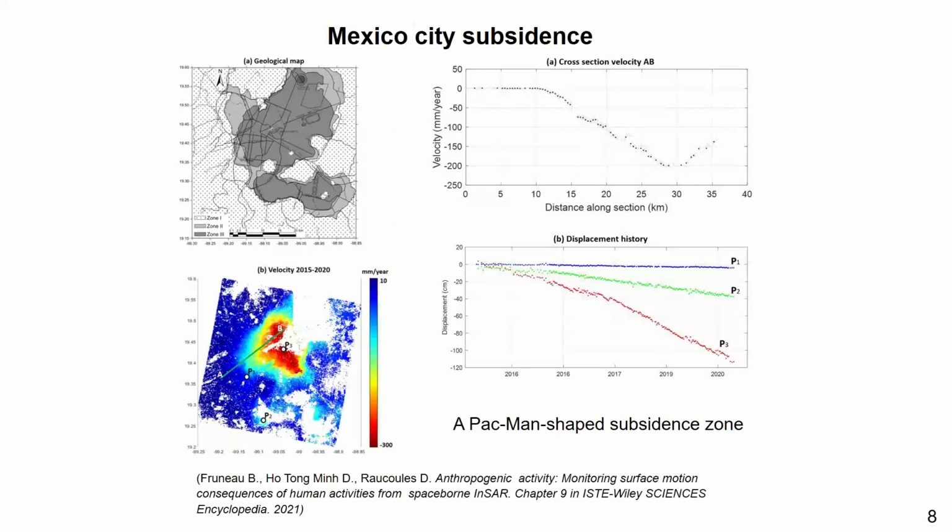We're trying some illustrations. For the technique, we first started with BSI, or the BS InSAR, with Mexico City here. Mexico City is actually one of the most famous problem subsidence cities in the world, because of the magnitude. Most Earth surface deformation in the world is relatively low, with a velocity trend of less than 10 millimeters per year, and very local, less than 100 square kilometers. But with Mexico City, the magnitude is a lot. It can go to 30 centimeters per year, and in a very large area like this one.